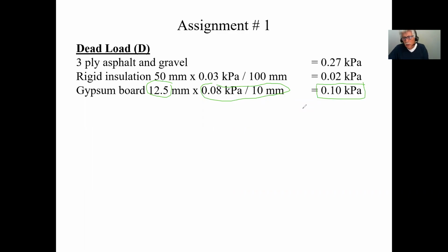And so this is approximately 2 pounds per square foot. So next time you go into a renovation center and you see gypsum boards that are 4 feet by 8 feet, so that's 32 square feet, and if it's half-inch thick, keep in mind that 32 times 2 is 64. That sheet's going to end up weighing about 64 pounds.